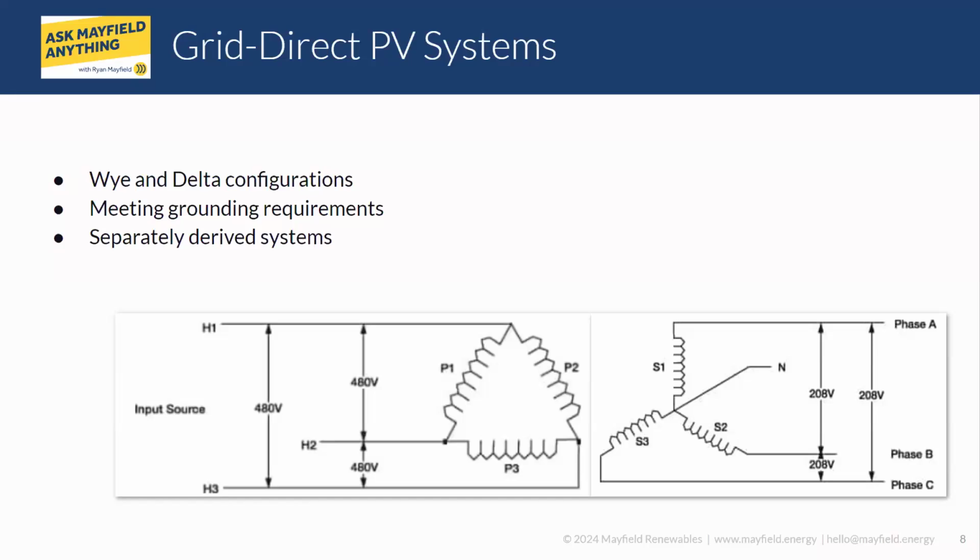Basically, there are multiple functions of an isolation transformer, but what it essentially means is that the primary and secondary have a galvanic isolation between the two. In other words, it's not a straight electrical connection. It's actually a magnetically coupled connection. So there are some inherent things to that from a safety standpoint. An isolation transformer is a current limiting device.